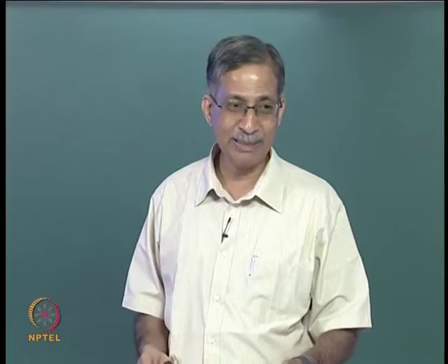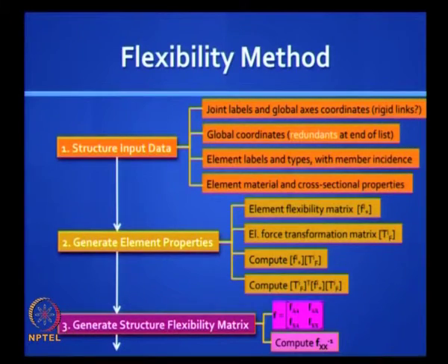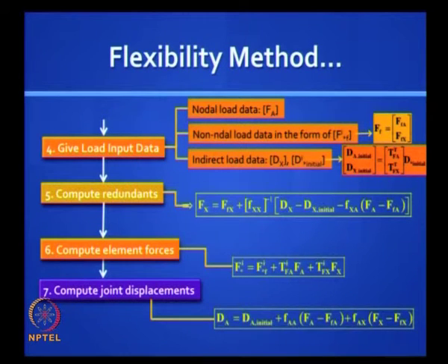The only thing is, different people will have different solutions till the end. The final solution should be the same, but the intermediate steps will be different. So the steps are, if you want to program it: input the structured data, generate the element properties, generate the structure flexibility matrix, compute Fxx inverse, because you have to invert Fxx in case you are dealing with a statically indeterminate problem, input the load data, compute the redundants, compute the element forces, compute the joint displacements.